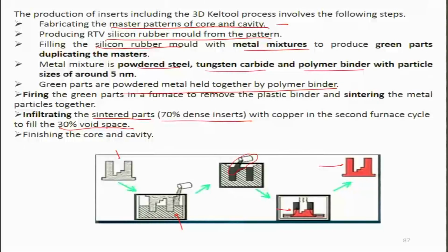So what we have learned is that through various surface hardening techniques, for example wire spraying and sintering, or even epoxy aluminum composites, or even some kind of polymer hard materials like tungsten carbide composites, etc., firing them to a temperature where the polymer goes away and there is local sintering between the metal. The objective that we are developing here is to produce an indirect tool. Now this tool goes and makes a cavity through a material which would otherwise be used for injection molding or some other means, without directly participating in the process. So this is how the indirect tooling business would be.